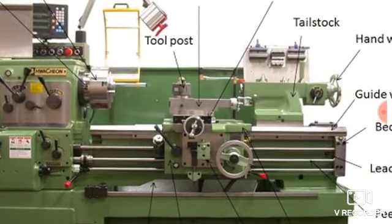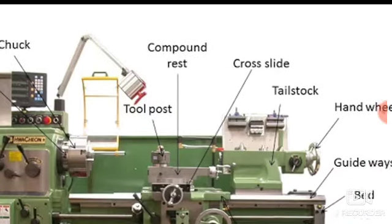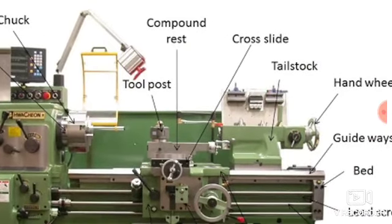After that there is a tool post for keeping your cutting tools. Here you can use a single point cutting tool, mostly on CNC lathe machine. On lathe machine single point cutting tool is used. So here you can keep either 4 or more than that single point cutting tool over the tool post. Then there is a compound rest. After that there is a cross slide for giving the feed in vertical direction, that is perpendicular to lathe axis.